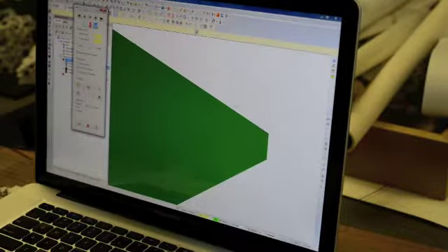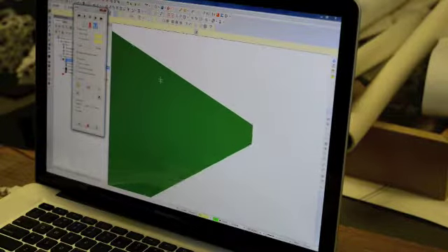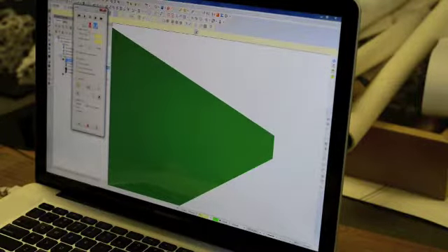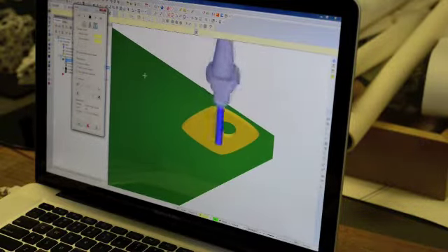to visualize that better. And then also when you do this, it's recommended that you verify it not using turbo, because the quality of the display over here will be really compromised, and it won't give you an accurate representation of the finish you're getting. And sometimes if there are conflicts like the tool holder crashing into your material, it won't show that as well. So I show the tool holder, and then you just hit the play button, and you can see